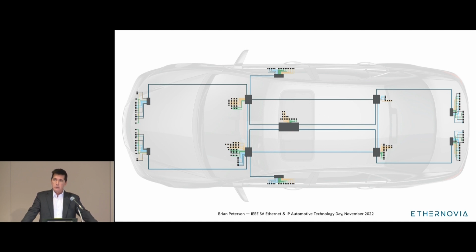People that have worked with me know that pointing out the obvious is one of my greatest skills. So the important point here is that we can have a controlling ECU that is essentially the brains of the vehicle, and it is taking advantage of the services of zonal ECUs. Those zonal ECUs provide aggregation for various signals and provide gateways to legacy networks.